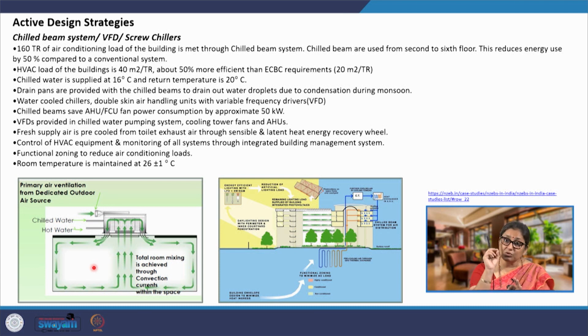But the most interesting part is that this is one building which employs mixed mode of air conditioning, cooling and air conditioning. So, during the period when the outdoors are comfortable, the windows are allowed to be opened by the users. The users can open the windows and the air conditioning system will not be run when the temperatures outside are comfortable, when natural ventilation and mechanical ventilation can be turned on.